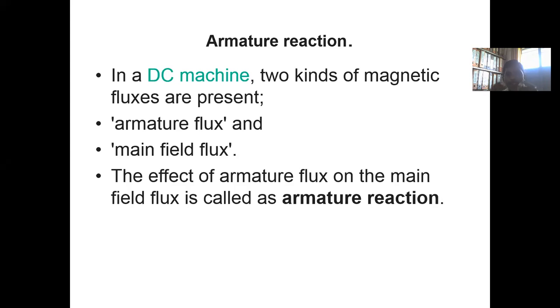In the stator, what are the parts? Does the armature come under stator or rotor? I can answer anyone. A DC generator or DC machine, or motor, whatever it is, is the same constructionally. Armature comes under rotor, whereas the main field flux, the field winding, will be in the stator.